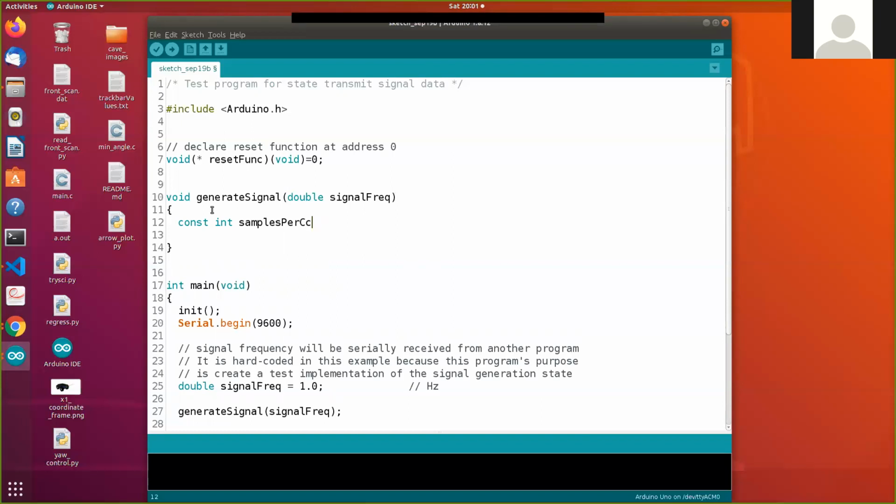Whatever, samples per cycle. I'm going to say I want 4 samples per cycle, so per period. And I'm basing this off of the Nyquist criteria, which tells us that we should be sampling at least twice the highest frequency. And so if 1 cycle is the highest frequency, if I take 2 samples from within that, so Nyquist says twice the highest frequency, so I'm using cycles instead of frequency. But it gets me the same thing.